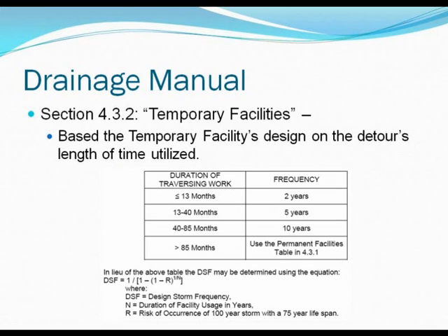The temporary facilities, now instead of just having a standard 10-year design event for your temporary facilities, you now can use the equation at the bottom of the table or look at the table we've provided, and that's for your construction timing. So if your project's relatively short, you can design to a much lower design frequency for your temporary structures.